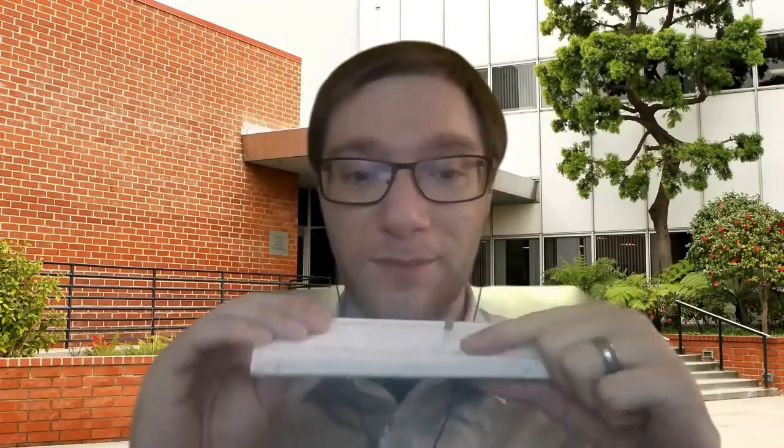And that's so that we can keep everything a little bit more clear in terms of diagramming out the circuits that we're building. And that's totally fine. It's totally normal and expected to bend the legs of these kinds of components. You just have to be a little careful about it and make sure that after you're done sticking this thing into the board, that the metal legs don't touch each other.